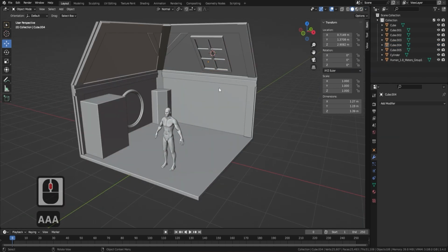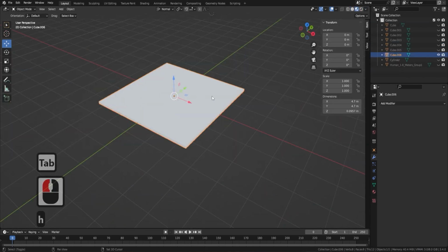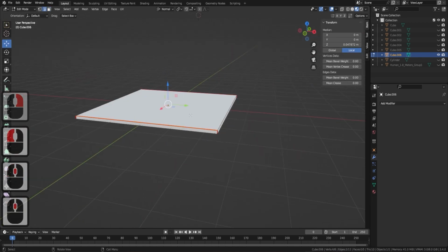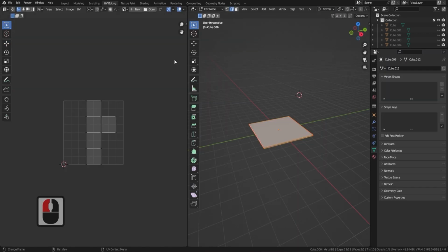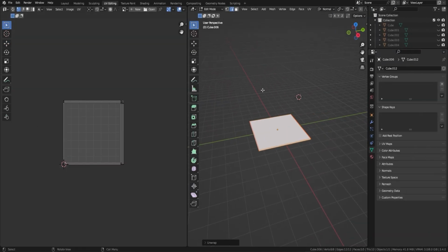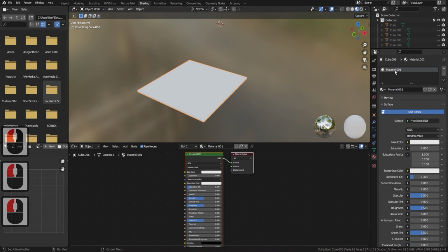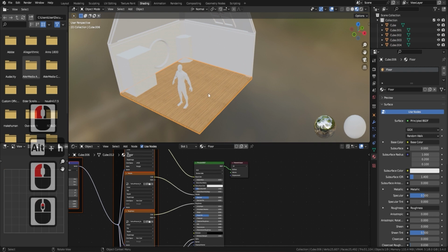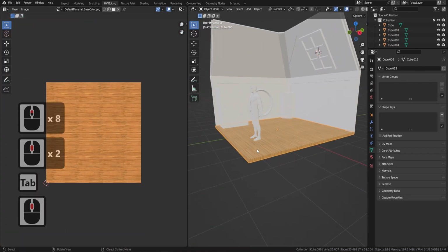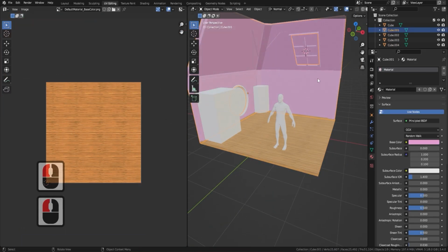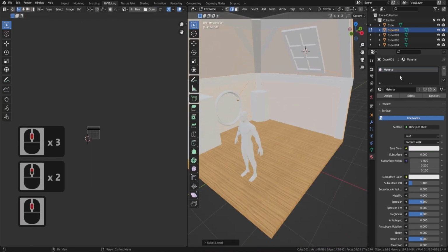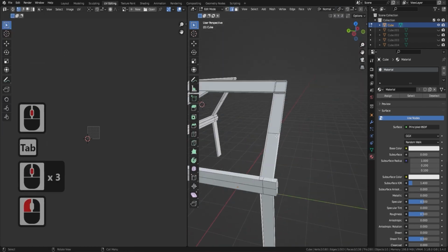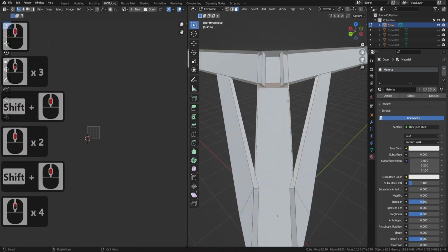Those atlas textures are not only the albedo or the color, they also come with the normal maps, the roughness, and metallic. This is also great because when you want to create your own rooms or environments, it's good to know how to use not only seamless textures, but atlas maps, UDIMs, and trim sheets. If you've got a good idea how to use all those, you'll be able to mix and match them depending on what you need. For instance, mobile games may be better off using atlases rather than seamless textures or even UV mapping them out in something like Substance Painter.